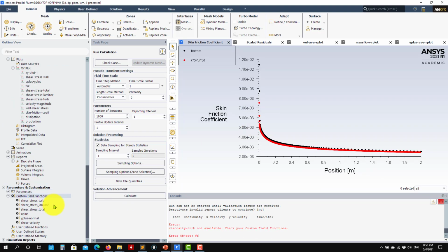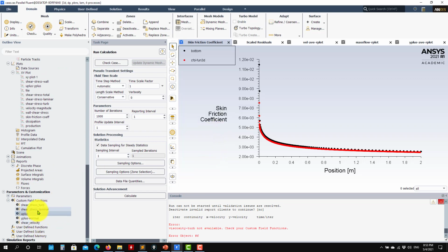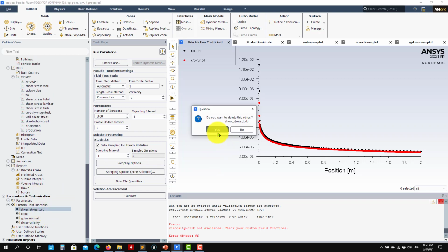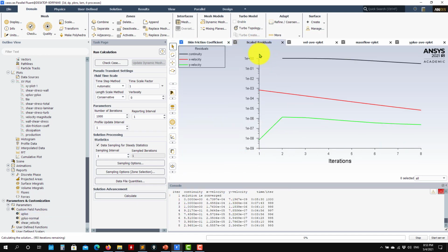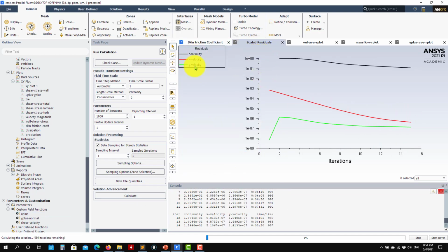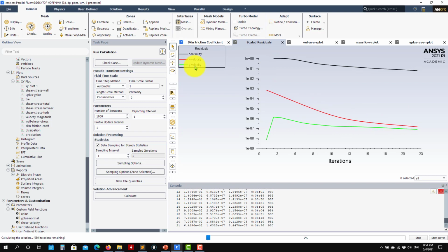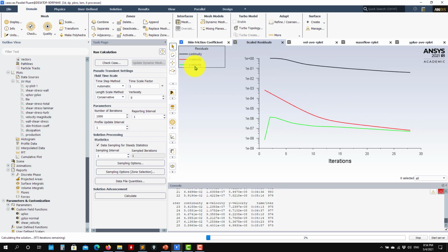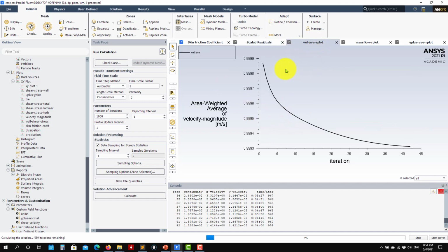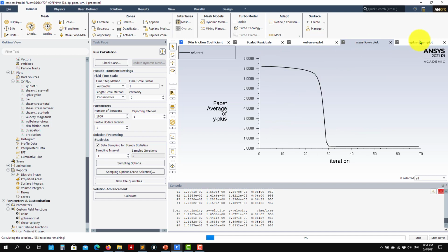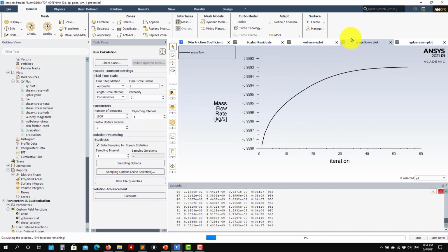Okay, so then we have some custom fields that also are not computed. So in particular, I need to remove this because we don't have the turbulent viscosity. So now I can run. See that we only have the exact equations, momentum, continuity. And it is iterating. And see that we have everything, but look at, well, this is not being monitored.